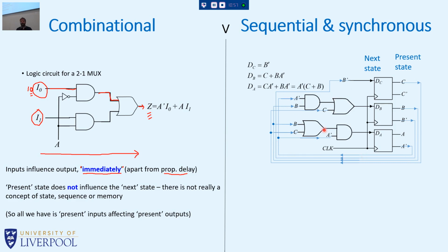And what you can see about this circuit is that it's got a present state that is collectively what are the Q outputs of the flip-flops. And we can see there's 3 outputs here, C, B, and A. And collectively, we could say CBA equals 0, 1, 0. All right, that's the present state of the system.